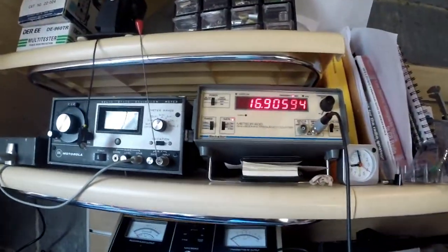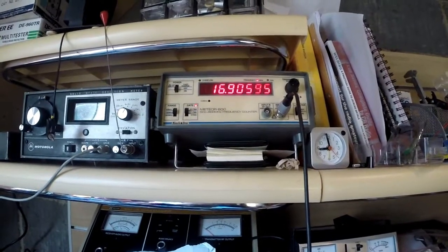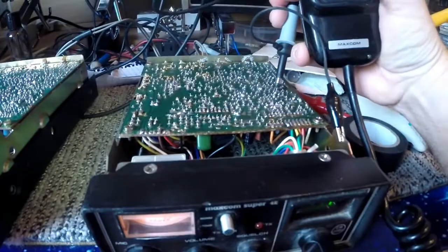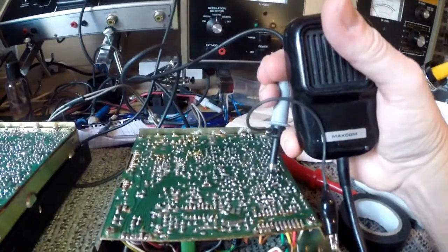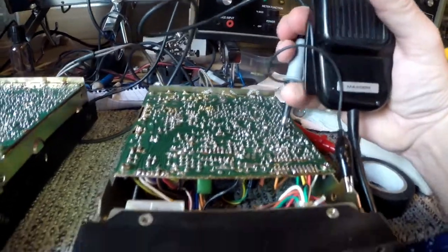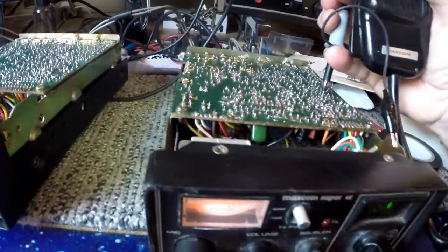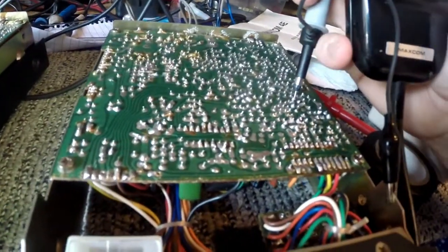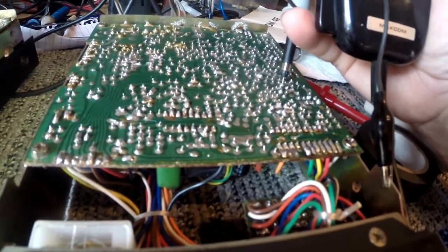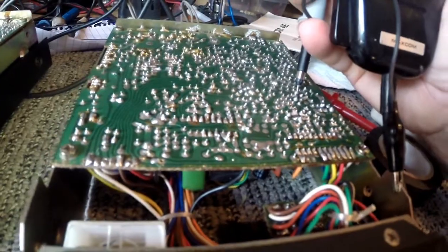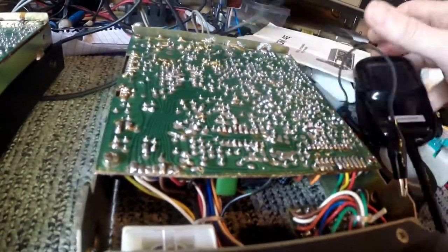Let's try it on the other radio. Right, so I've got the radio there. I'll key the mic now. Nothing. And you can see we're not going into TX. We've got no TX at all, and we've got no down mix signal. So again, the radio won't lock because we haven't got that TX signal either. So we need to look at the transmit receive circuit now.